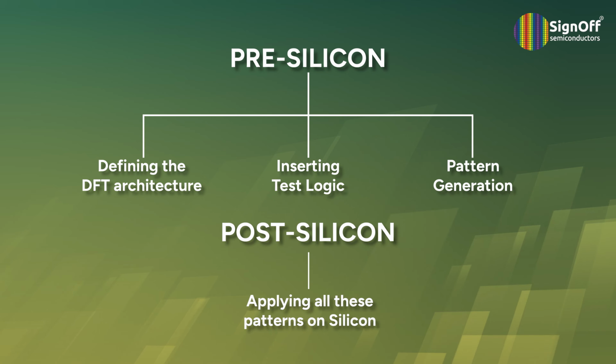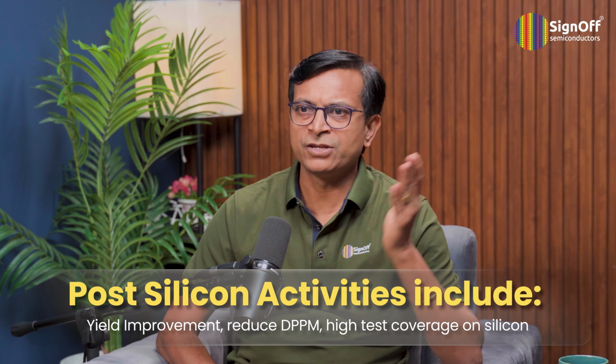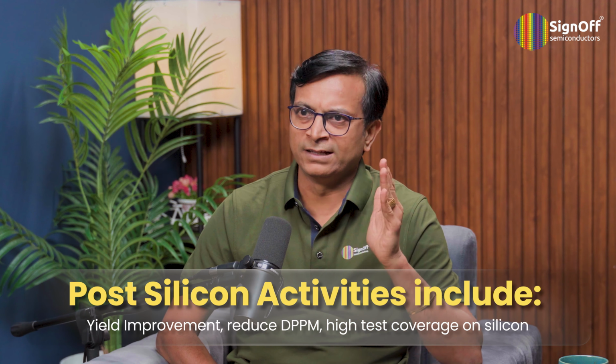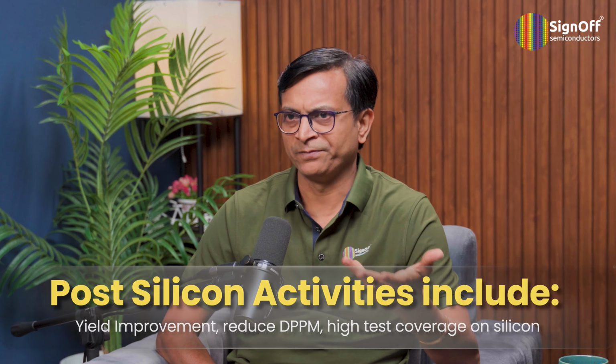We use the ATPG method to generate a lot of patterns. And the last step is applying all these patterns on silicon. Once we get the silicon, we take it onto the ATE, the tester, apply all those patterns which we have generated, and make sure that the physical defects are getting identified. We also work on yield improvement and making sure that the ppm is very low. We try to get good coverage on silicon. So we keep doing all these activities.